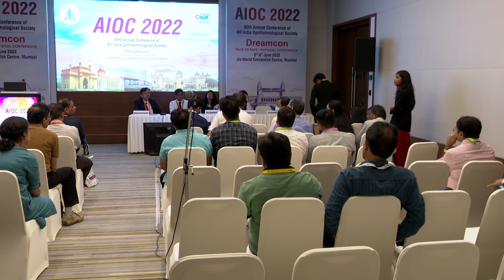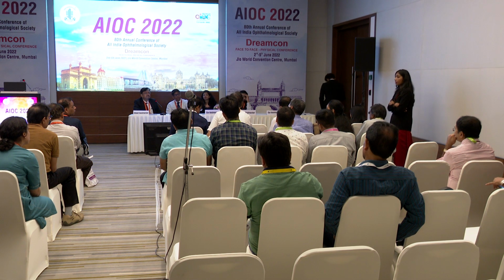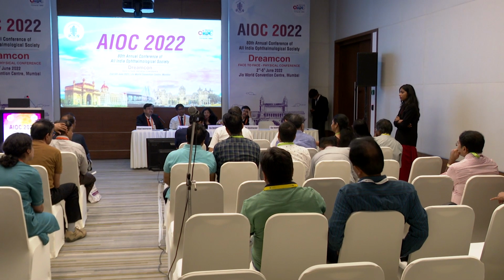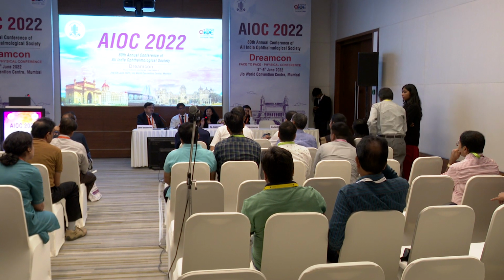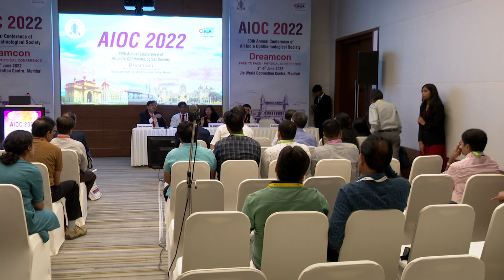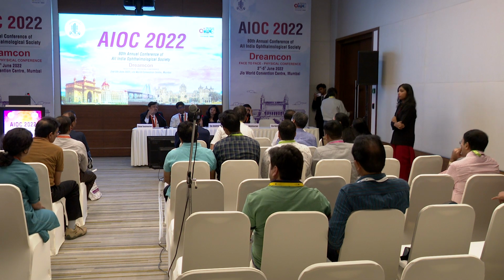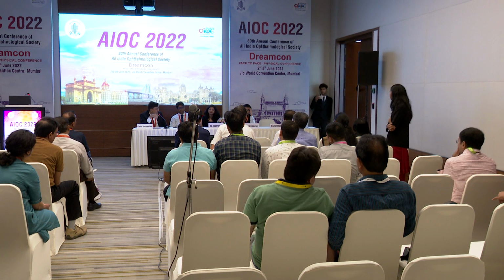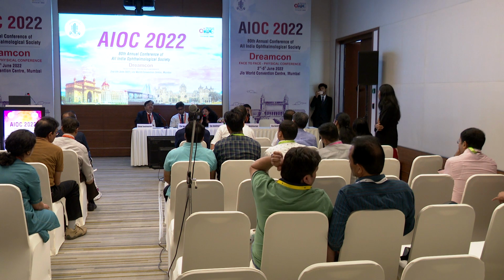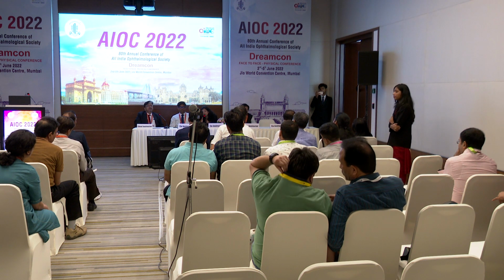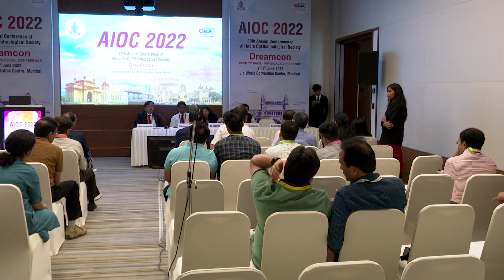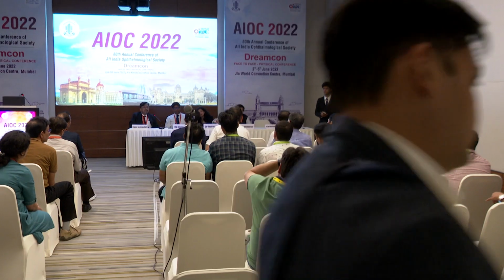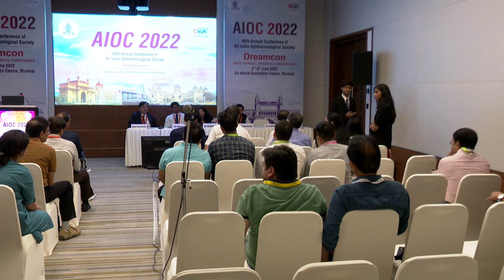Must the scrub area be before the operation theatre, or can we make it in the operation theatre? No, outside the operation theatre, adjacent to the theatre, inside the OR complex but outside the operating room. See, the operation theatre is divided into 4 zones, so this comes in the zone just before the complete sterile zone, right, Supriya? Yes, and in the scrub area there will always be water, however much precaution you take, so you cannot have that inside your theatre. It has to be outside the theatre, but inside the OR complex, where your block room and other rooms are located.